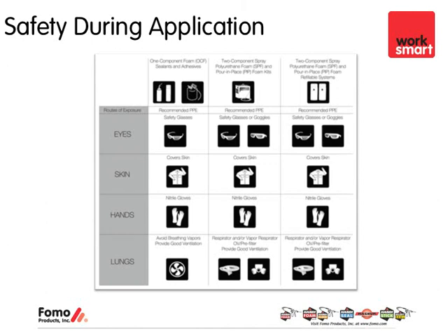And when installing this product, the requirement would be safety glasses. You want to make sure that your skin is covered as well as your hands with nitrile gloves. You want to make sure that you're going to apply the foam where you have proper ventilation. Now, if you look at the other two columns, these would be the two-component polyurethane, spray polyurethane foam low-pressure products. One of them in disposable packaging, one in refillable. Same technology, same chemical makeup.